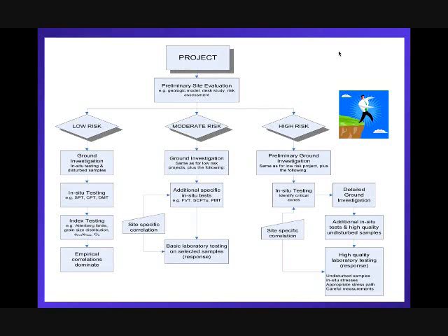You might also do some basic sampling, sort of Shelby tube sampling, not the highest quality, but with basic lab testing, and then link those results back to the in-situ testing. Undisturbed samples, Shelby tube samples often being the most popular.